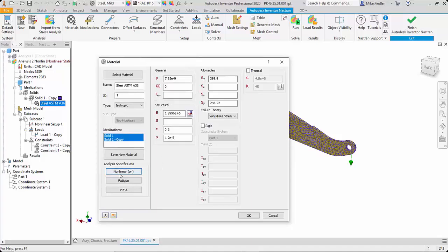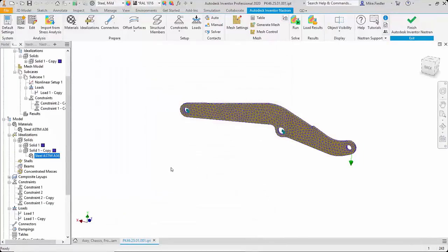So having chosen that material model, now you can see it says that the nonlinear material is on. So that way, if we were to apply a load and we exceed the yield, now it knows that it needs to start following the slope defined by that tangent modulus. At that point I can go ahead and say OK.